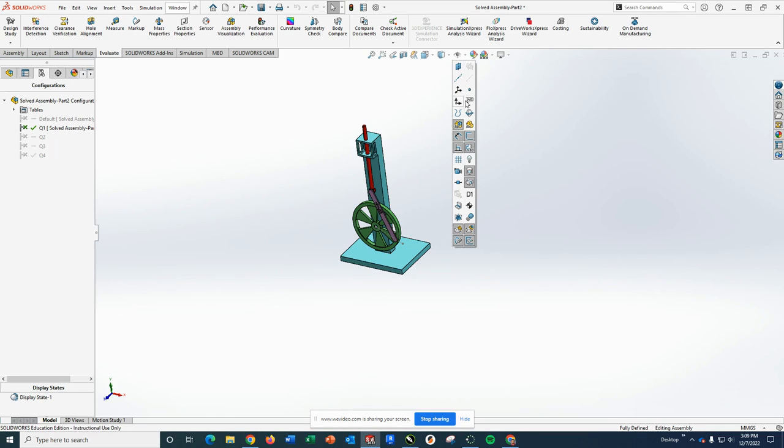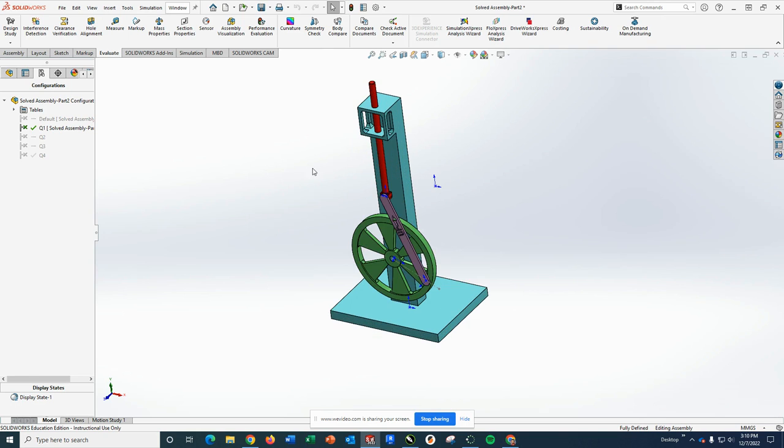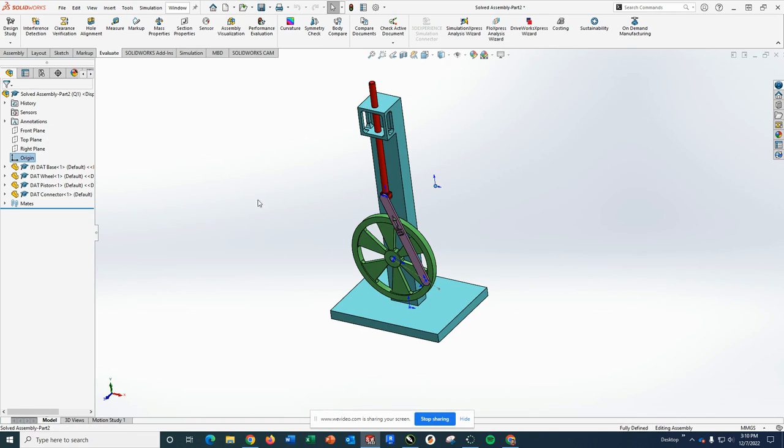First things first, just so that you know, this assembly is kind of randomly placed in space. Now, if I come up here where the eye is hanging into my area and I turn on the origins, you'll notice the origins for the various parts themselves do come up, but I also have this random origin floating in the background. That is the origin of the assembly itself. I can tell that because if I click on the origin, you can see that is the point that is selected. So that's where the origin itself is.